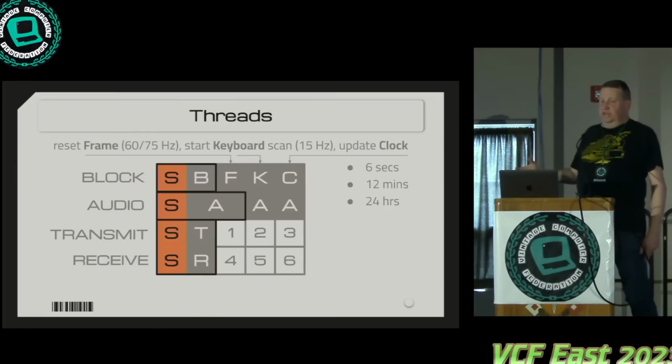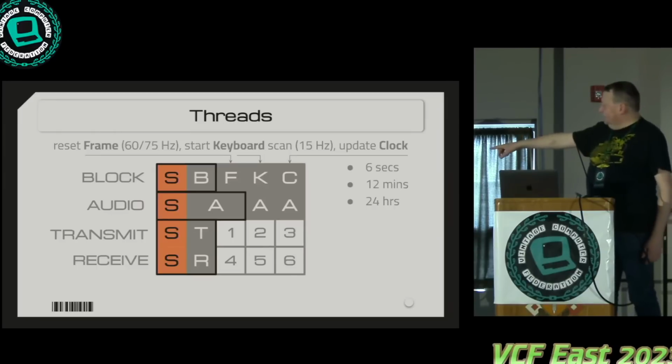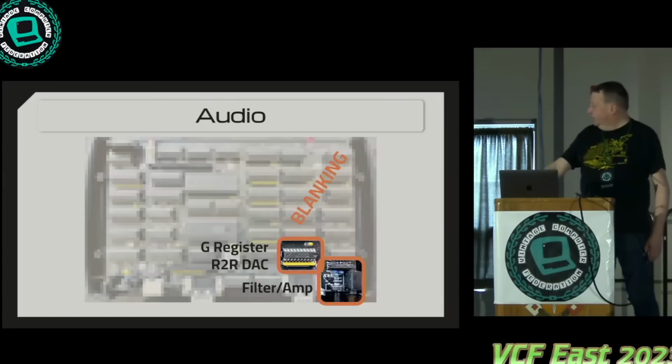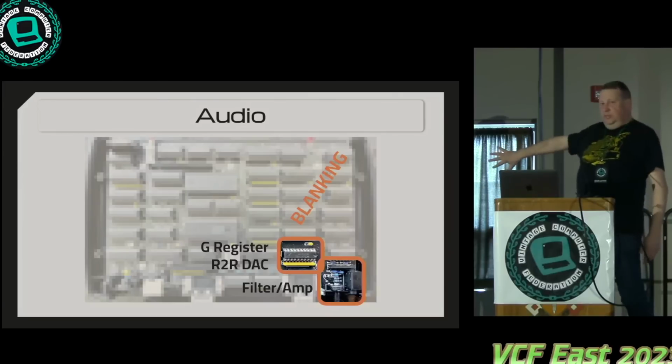And then when you turn on the actual serial communication, it does sample the serial, but it doesn't do anything with it. So you have to consume a cycle in order to handle the actual serial. And so that's what's happening there. So not all of this will get turned on at the same time, but if you do, you only end up with 6 available to run your CPU. So the more features you turn on, the more you take away from the resources to run the actual code.